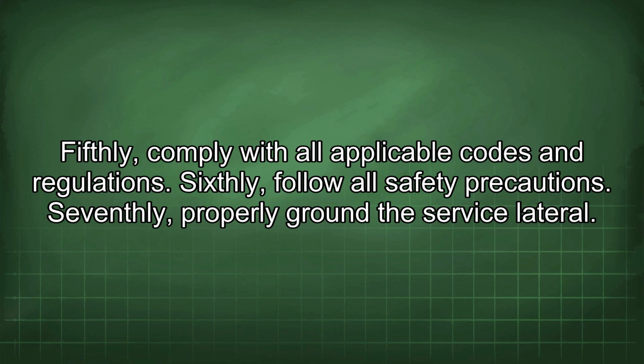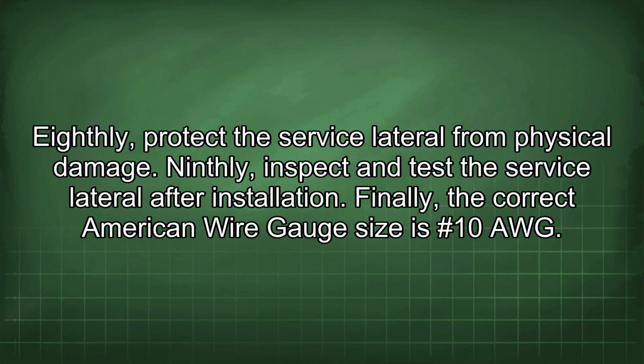Sixthly, follow all safety precautions. Seventhly, properly ground the service lateral. Eighthly, protect the service lateral from physical damage. Ninthly, inspect and test the service lateral after installation. Finally, the correct American wire gauge size is #10 AWG.